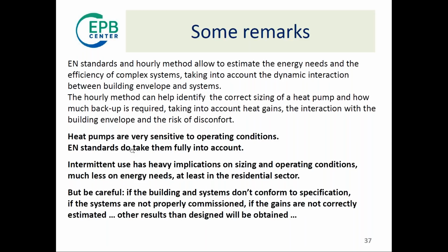And another remark that we had is that the intermittent use has heavy implication on the sizing and the operating conditions. So it's not just a question of, well, I turn off during the night and I save 5% energy. The question is that you need a bigger system and you have a discomfort. So this also is another consequence that is quite important and much easier to deal with when you have an hourly calculation.